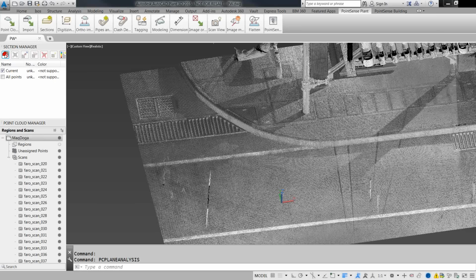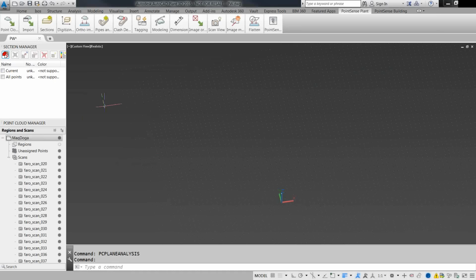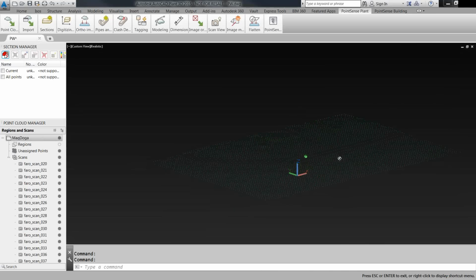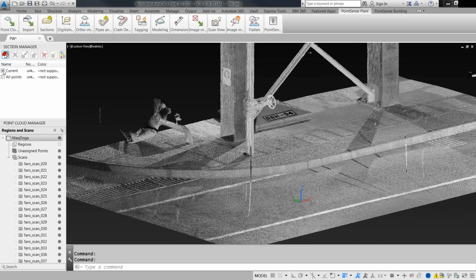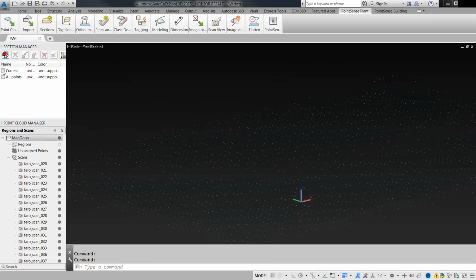And you should see there we go, a little longer than it usually takes. That's a good thing if that was still only 3 seconds. But here's a grid of points for everything on there. And if I turn the cloud section back on, you can see all of that stuff, the steel, you can see the plumbing here, everything like that. It got disregarded. And it's not like we actually just made an empty area on the grid. We actually went ahead and plotted the grid below it. We just disregarded a certain elevation.